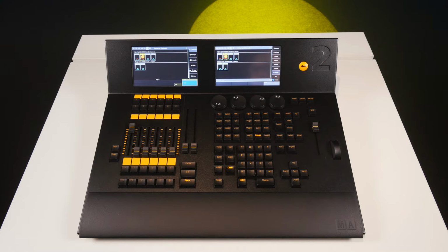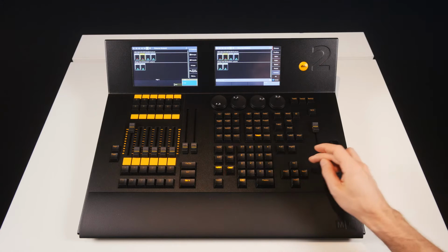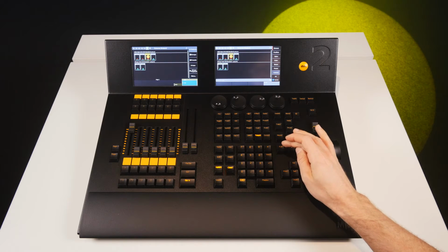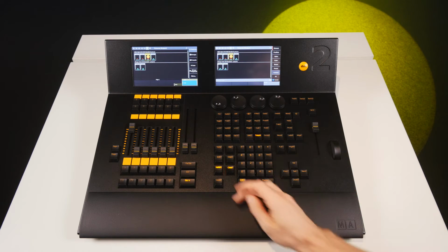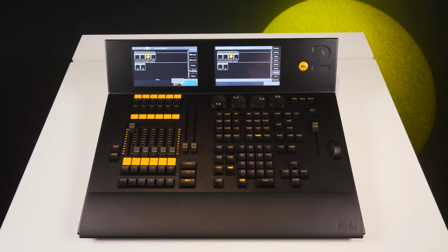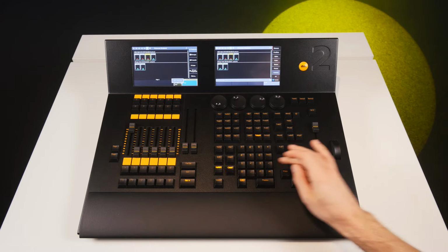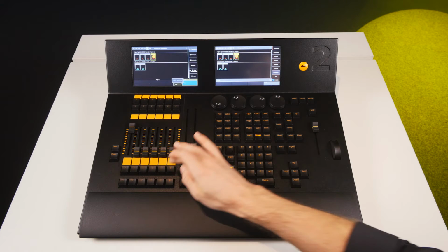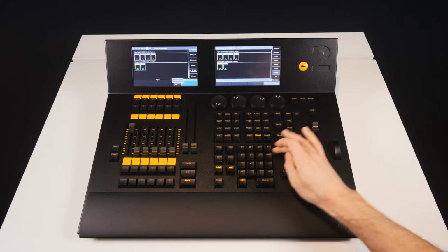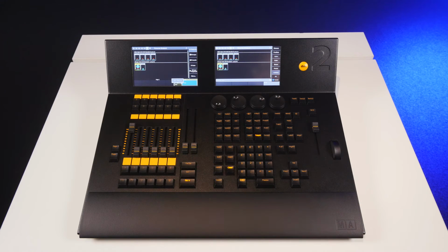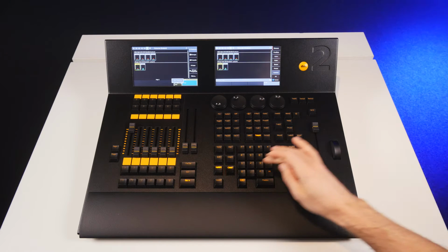Now we'll repeat this process with all of our fixtures. Point to turn the fixture off, next to select our next fixture, Full to turn it on, Store and the button below the fader to store it. When we have worked our way through all the fixtures, we'll press the Clear key twice to clear the programmer.